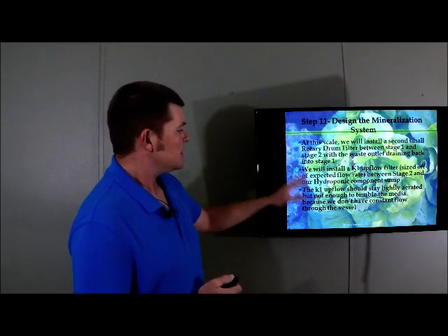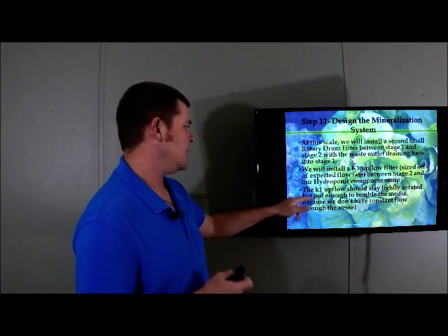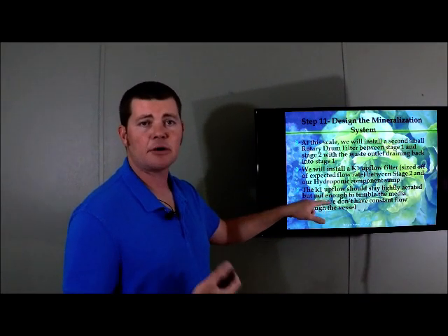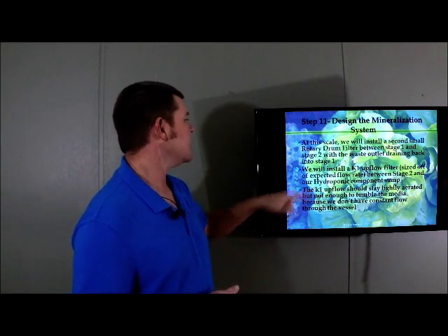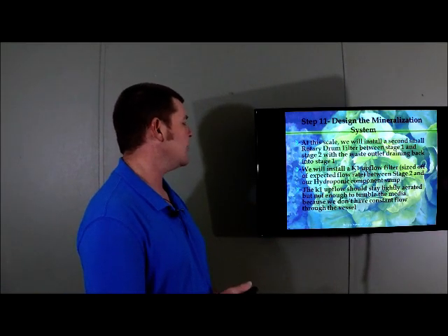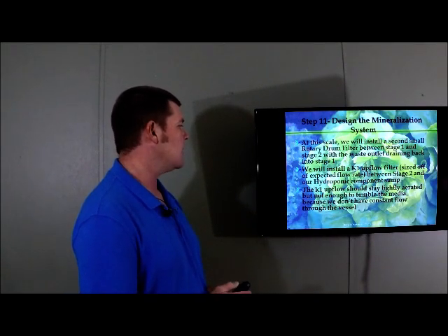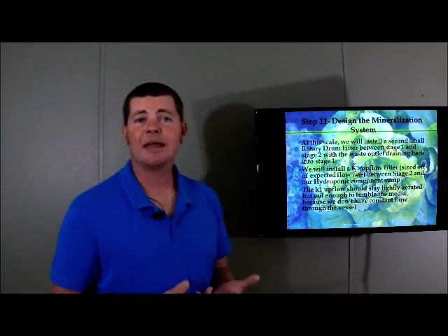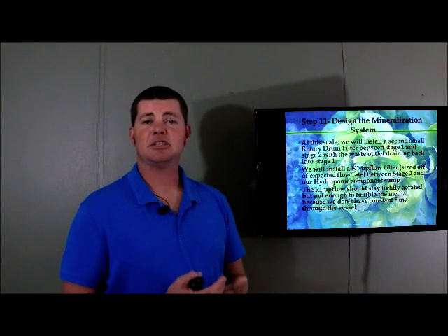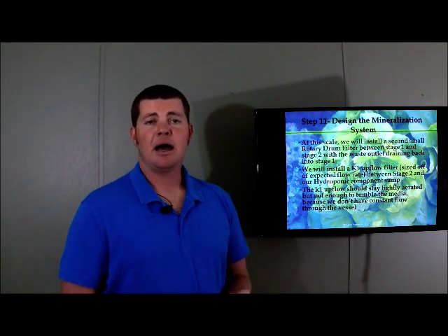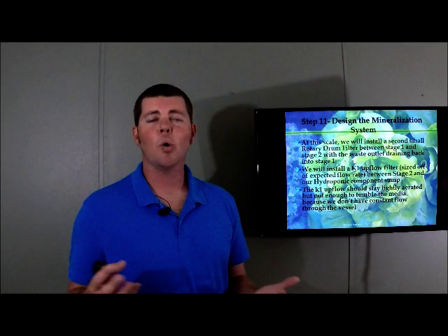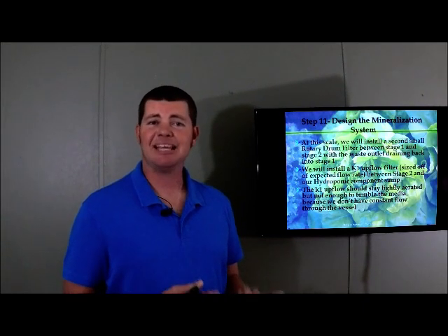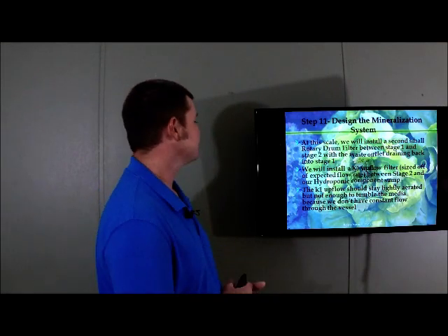Okay. Something different than we're doing in some of the other designs is the K1 does not constantly have water flowing through it because it's not a recirculating design. So the K1 upflow should stay lightly aerated but not enough to tumble the media, because we don't have constant flow through the vessel and we don't want it to go anaerobic on us. So put a small air stone, I would size it at 1/4 the size of your normal size so that it doesn't tumble the media but it keeps it aerated, okay?